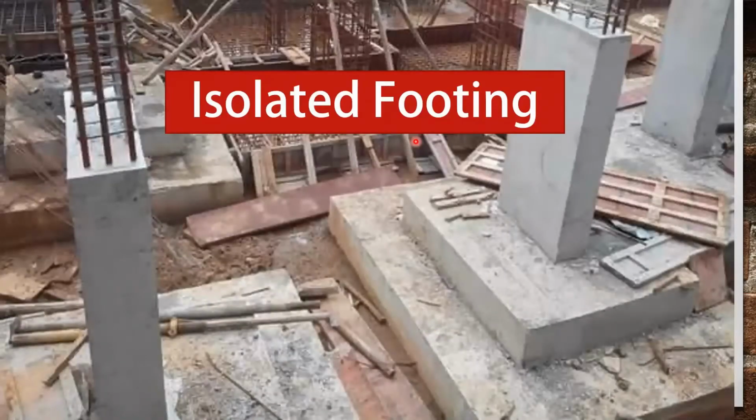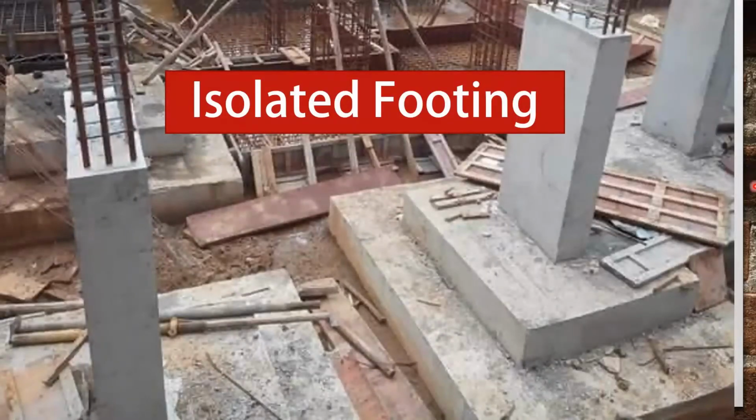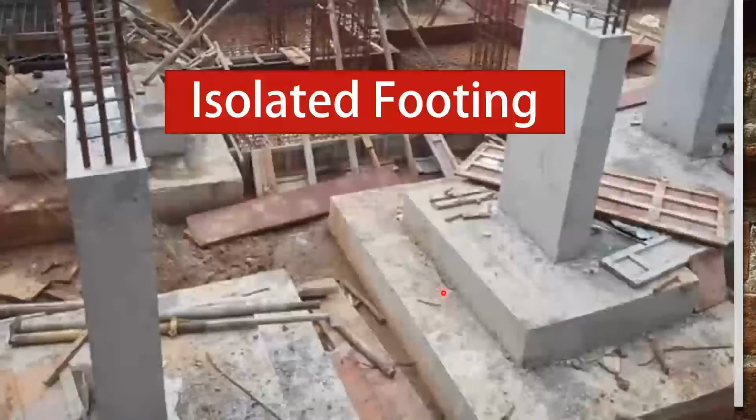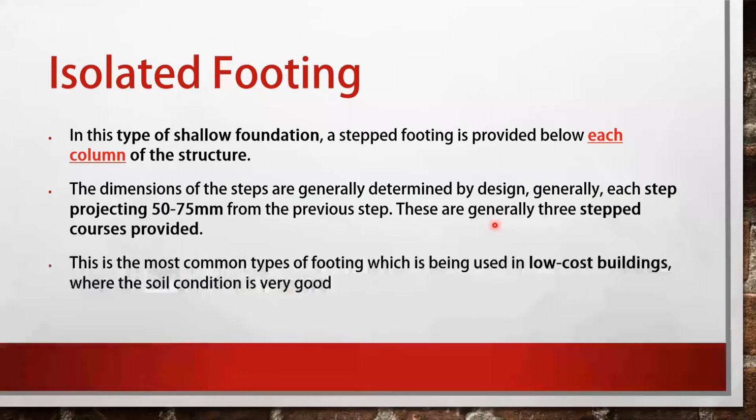Over here you can see an image of isolated footing. In this type of shallow foundation, a stepped footing is provided below each column of the structure. You can see for each column we have a single footing, and these footings are stepped. Basically these footings are stepped in three different layers, and each layer of the footing is constructed at a difference of 50 to 75 mm. This is our first step and this is our second step, so this step will have a width more than the first step by 50 to 75 mm. This is the most common type of footing used in low cost buildings where the soil condition is very good. So that was all about isolated footing.